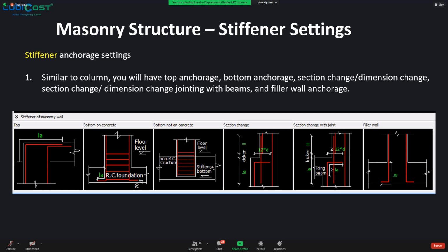So you can have reinforcements plunging up from your brick wall down to your slab or whatsoever, right? You can do that, but we don't usually do that, because our brick wall is usually supported by stiffener instead of the brick wall itself, right? So that's the situation. Now, let us go through how to play with all this information.